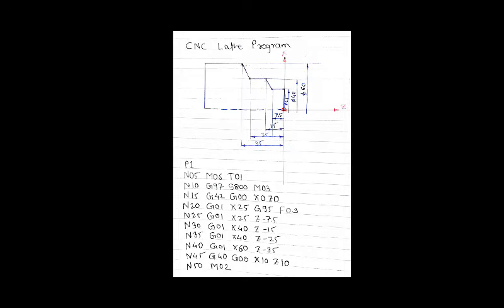Now let us see the next. Here the tool's position is given in the N15 block. If you see the coordinates, X0 and Z0 are here. That means the initial position is over here. Also I am going to repeat one thing. In programming there are three major parts: part 1 program setup, part 2 chip removal, part 3 system shutdown. Here we did the program setup. Now let us move to the second part.